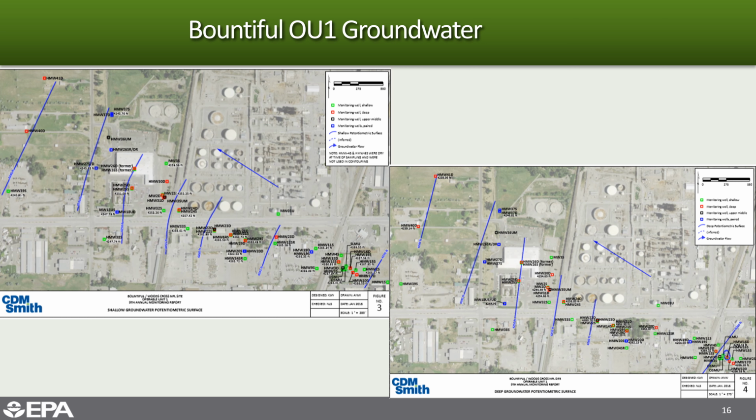Now the site, in terms of depth to water, when I show the shallow contours, most of the wells that we talk about that are in the quote shallow portion of the aquifer are screened on the order of 20, 30, 40 feet deep. The deeper well screens shown here, many of them are screened in the 50 to 75 range, with several leading up to more than 100, about 100 feet deep. So shallower portions here, deeper portions, but the groundwater gradient and direction are pretty similar, shallow and deep portions at the site.